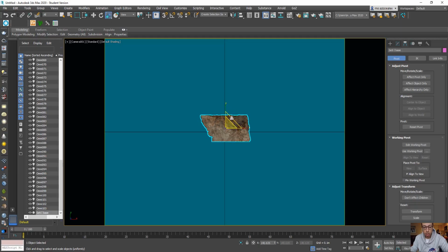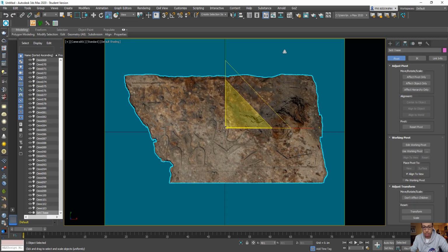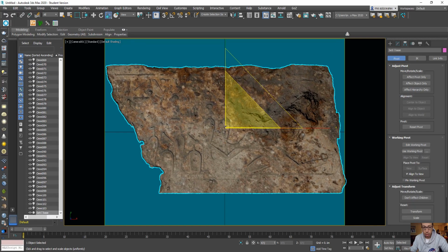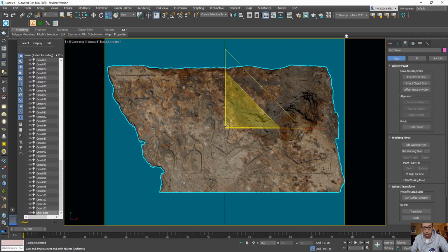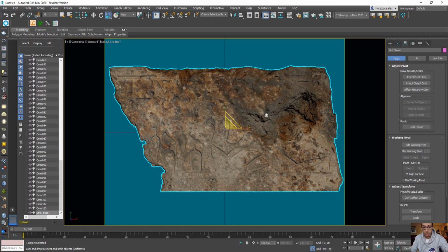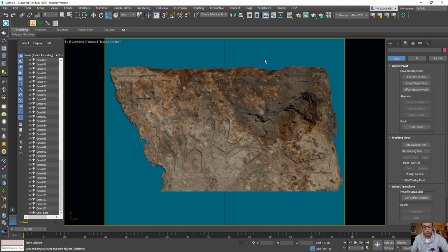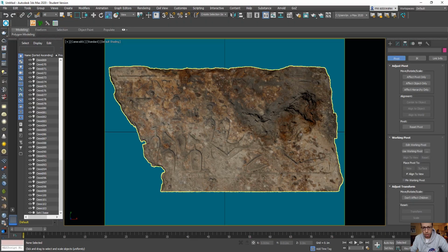So I will use the scale tool, whose shortcut is R, or from here, and make sure I'm in the middle here to resize it in the 3 dimensions, and I will scale it up again till it's in the middle. So, it's not like that. It's a very important thing. Another very important thing, this model is supposed to be on the ground.